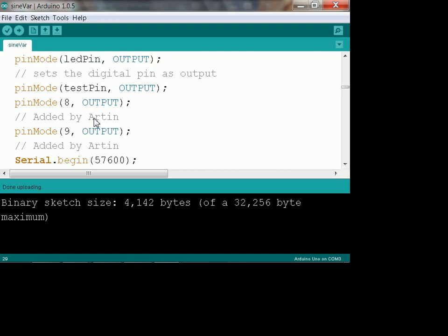It goes through a resistor, R5, then follow the other end of R5, and it goes into an inductor, L1, then follow the other end of the inductor, L1, and it goes into a bypass capacitor that says 10 nanofarads, and that's accurate and correct. And then if you follow the other end of the 10 nanofarad capacitor, you'll see it says audio output.